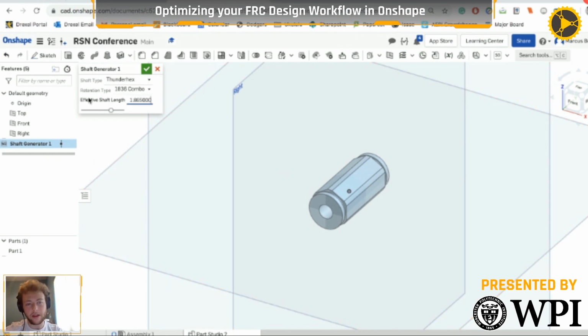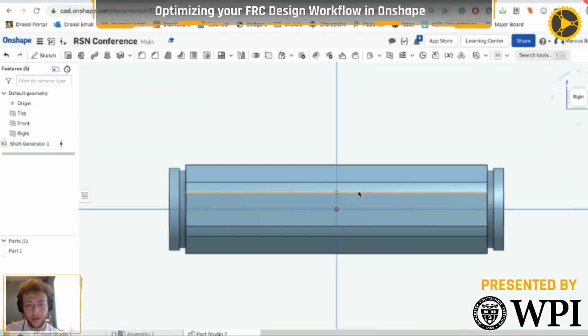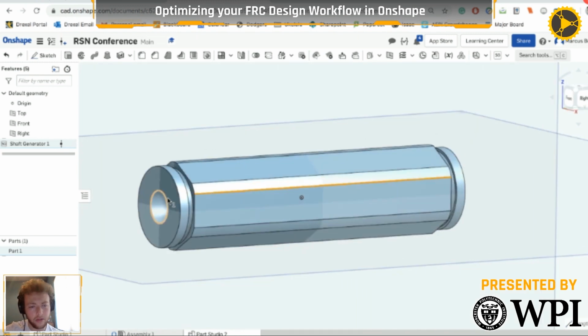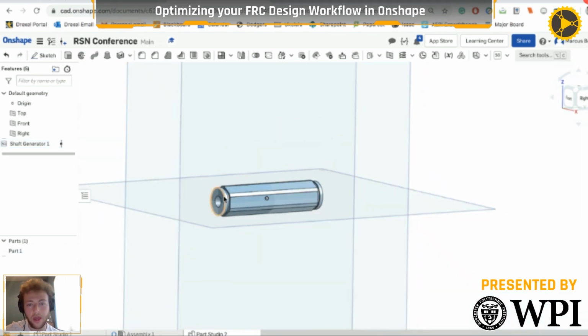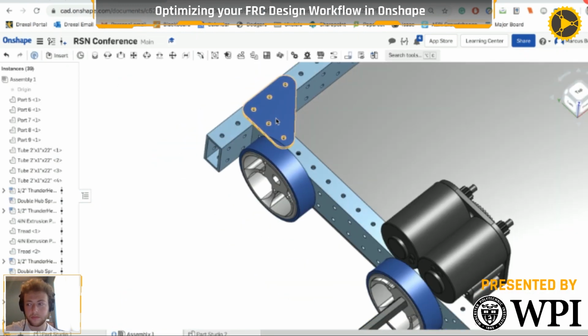Then I'm going to add in the effective shaft length, which you might remember we copied from the part prior. If you notice over here, this length is what we want for the effective shaft length. That is that number that we copied before. And then the snap ring groove is dimensionally accurate to the snap rings we typically use from McMaster. And then this probably should be a 0.201 hole, which we could then grab and do all of that stuff. So that's a clearance for a 10, I assume, or an 8? That's a tap hole for a quarter 20.